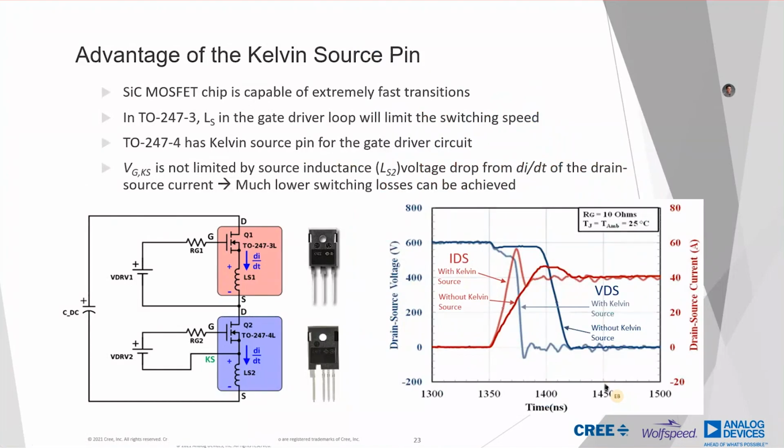So the next aspect to look at is actually the package of the MOSFET itself, and this is very critical here. TO247 packages, everyone's familiar with them. They've been around forever, and they're great as long as you're not trying to switch fast. With silicon carbide, these leads are inductors, reaching up from the board to the actual die in the package. And so that inductance plays into the circuit diagram that I just showed, and it's actually part of the device.